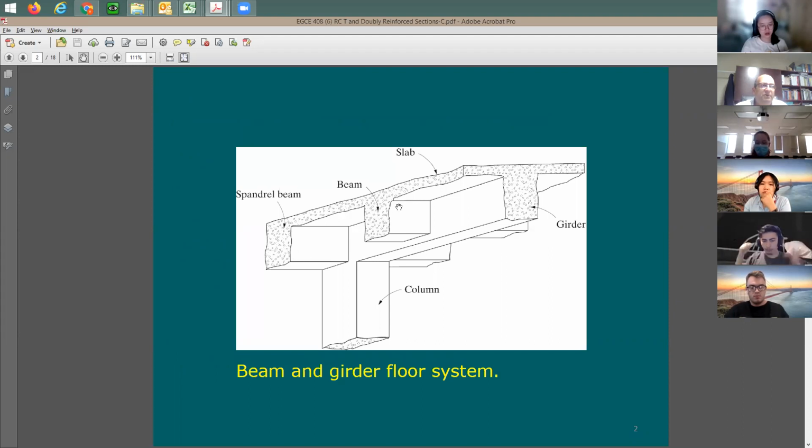As you see here, a beam is usually going to be a T section. We said if the neutral axis is going to happen within the flange itself, it's going to be rectangular. So this section, or the slide set, is going to cover the cases when the neutral axis is falling below the concrete slab.